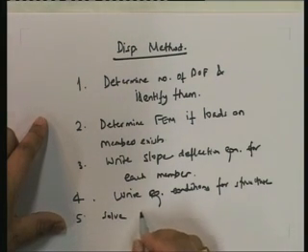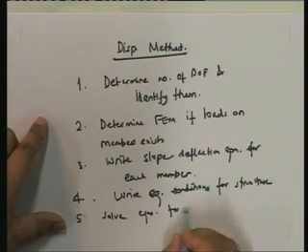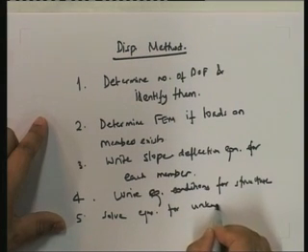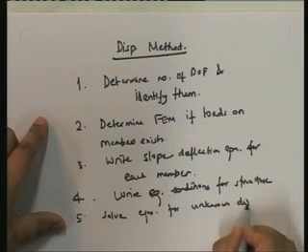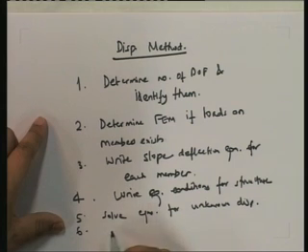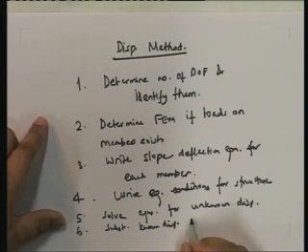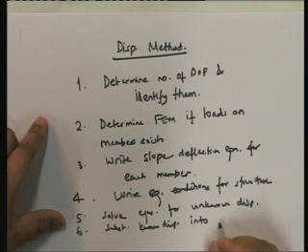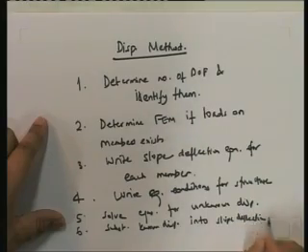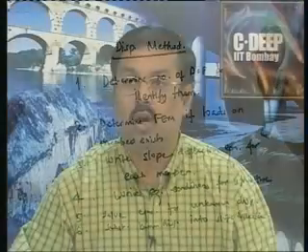Solve equations for unknown displacements. 6. Substitute known displacements into slope deflection equations so that you can get your member end forces, member end moments, and once you get your member end moments, you should be able to solve.